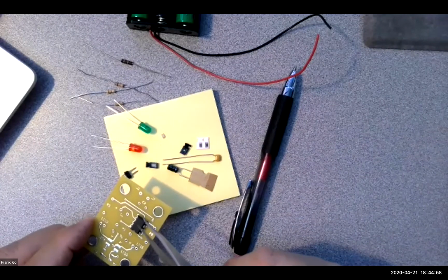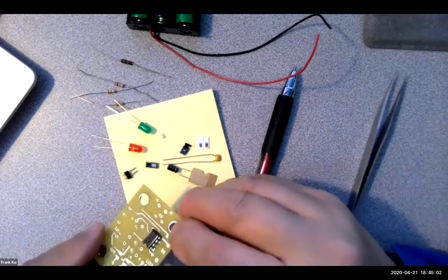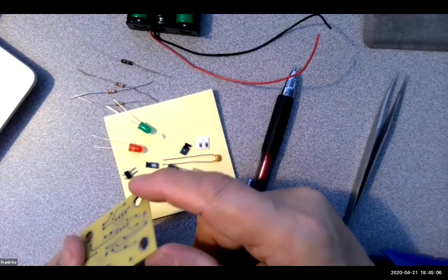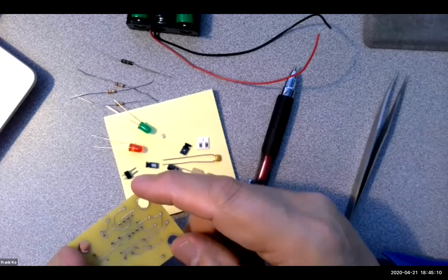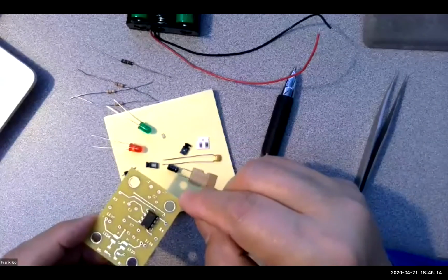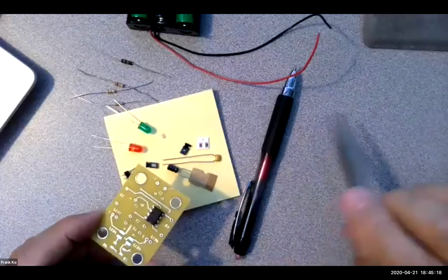If you put this guy in backwards and you solder this guy in backwards, you're toast, because it's going to be incredibly difficult to unsolder 8 pins on the backside to remove this in case you happen to make a mistake and wire that chip in backwards. Okay, so the chip has to go in with the correct orientation. The notch is facing your LEDs.